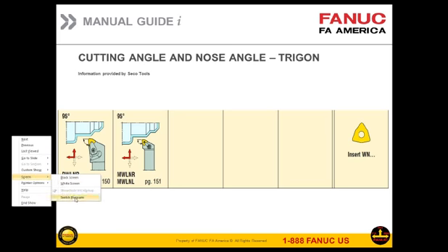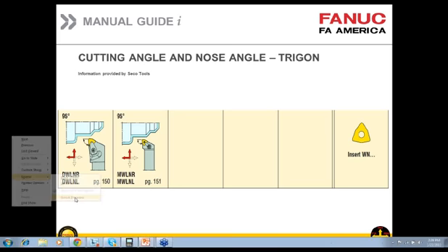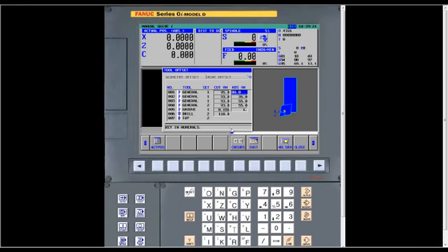Now at this point, we'll go back to NC Guide. So that's the type of information you enter on these first four. I've got turning tools, so 35 degree with a 93 degree cut angle, and 93 degrees with a 55. Those are all my turning tools. Basically a rough, a finish, and a semi. With those tools, you ought to be able to get into almost anything.